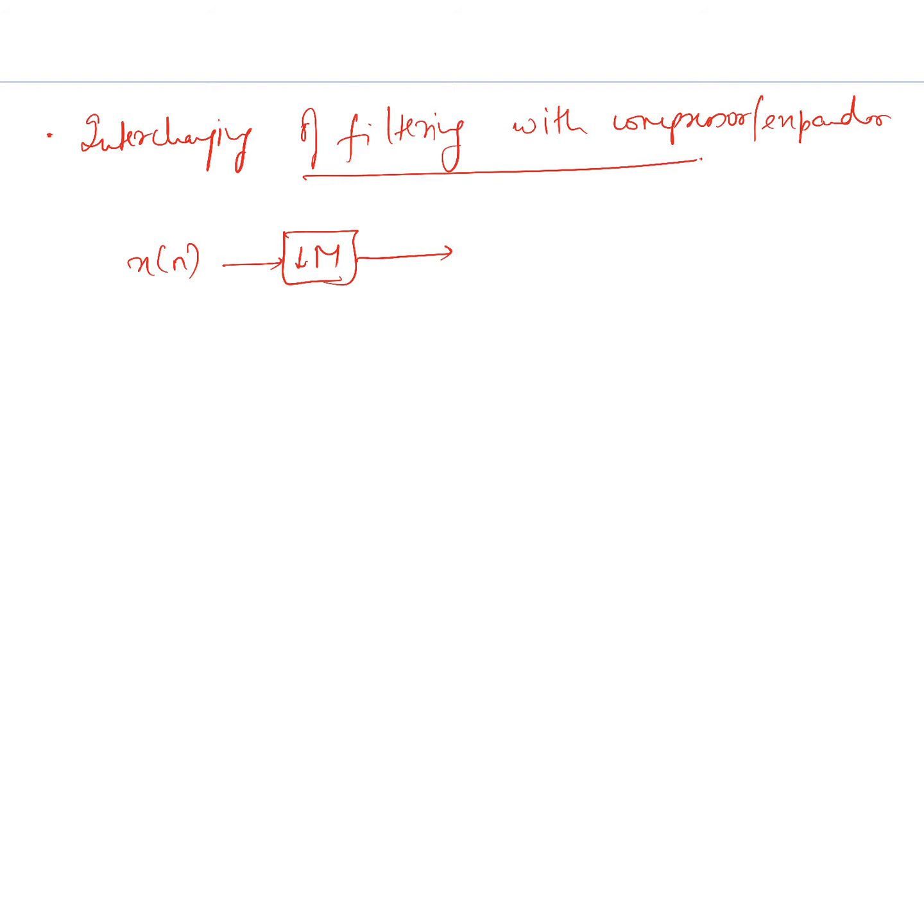For the moment, let's call this signal xa of n, because if you recall, we have denoted a downsampled signal by xd of n. And then we use some filter h of z. Now here, if you recall in the previous topic of this compressor, we specifically designed this filter as a low pass filter with some specific gain and cutoff frequency.